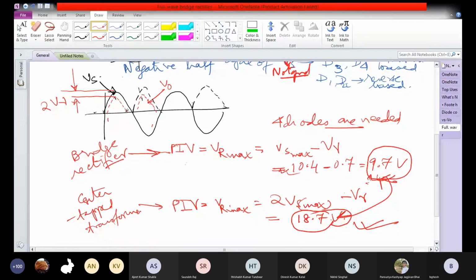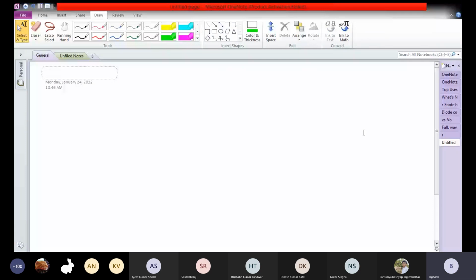In addition, as we see, only half the number of turns are needed for the circuit with the bridge rectifier. Okay, so these are the two important advantages of the bridge rectifier over the one with the center tap configuration. Now let us go to finding out the ripple, computing the ripple and finding out the filter capacitance needed to control the ripple.